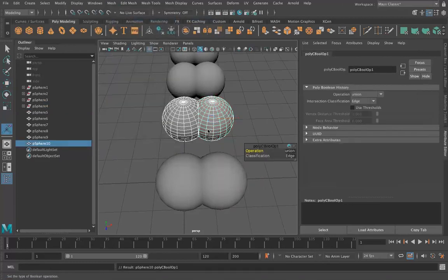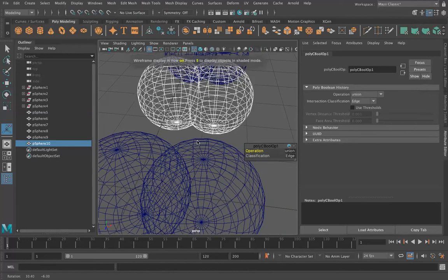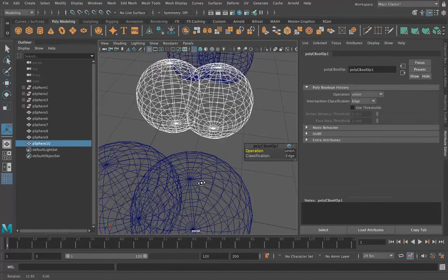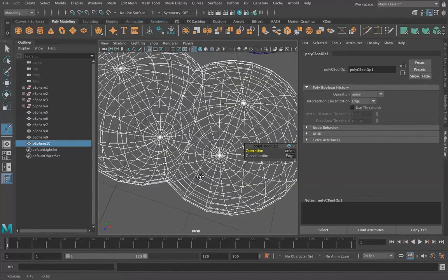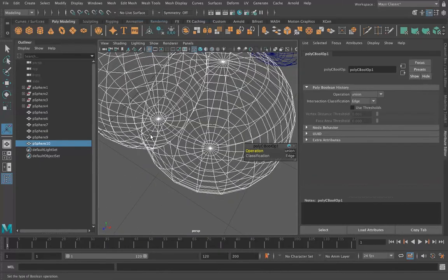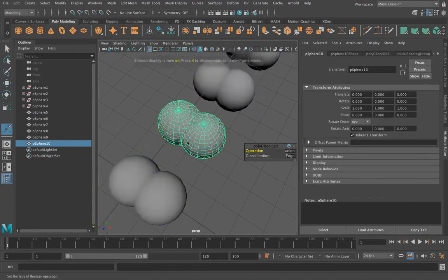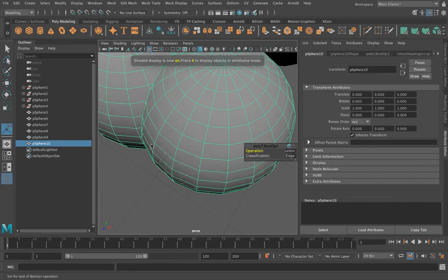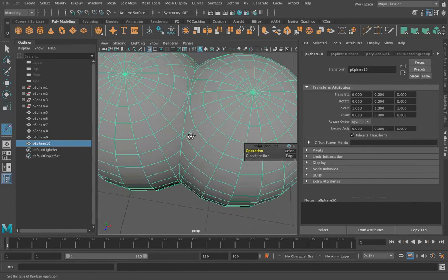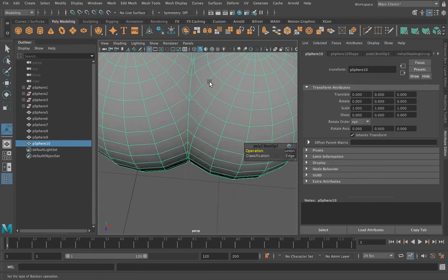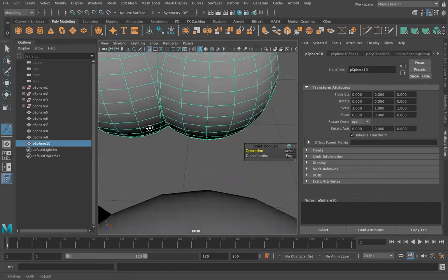So now let's hit wireframe mode, and now you can see that where the combine has maintained all that overlapping mesh information, a union bool deletes all of the information of the meshes, like where they intersect, the interiors of them. And this is a really great way of generating a form that has a kind of topology maintained, where we just have the surface of the object.